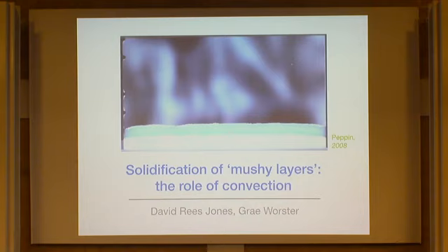So this is a salt solution. This is a layer of solid beneath its eutectic temperature. This is a partially molten layer containing liquid in the interstices of a solid matrix, and this is a purely liquid region. And the experiment is run where this solidification device is pulled between a cold and a warm heat exchanger, creating a temperature gradient. And it's pulled at a prescribed rate, which is varied over the course of the experiment. So let's have a look.